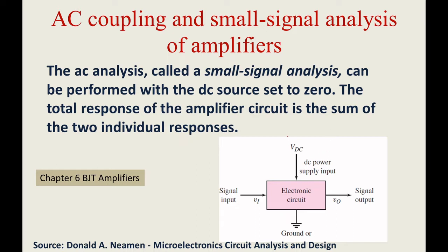Seeing the diagram given here, this is your transistor. Here I am providing a DC supply, and the small signal is your AC input. This signal gives a small input that is amplified. In terms of common emitter, you have only the phase shift with the magnified output. The circuit is grounded. Another thing to remember: everything we discussed uses the common emitter amplifier for our reference.